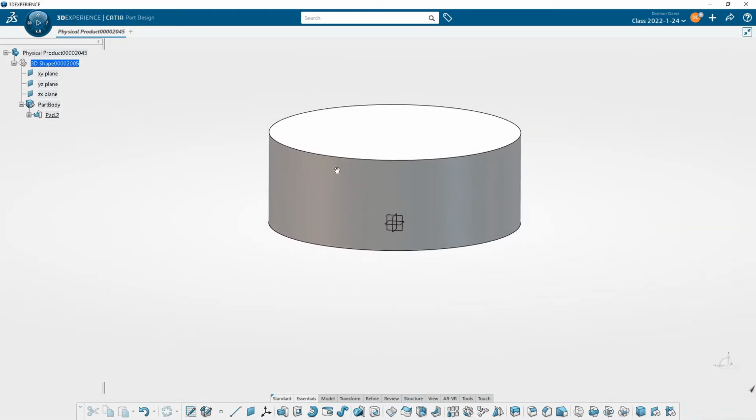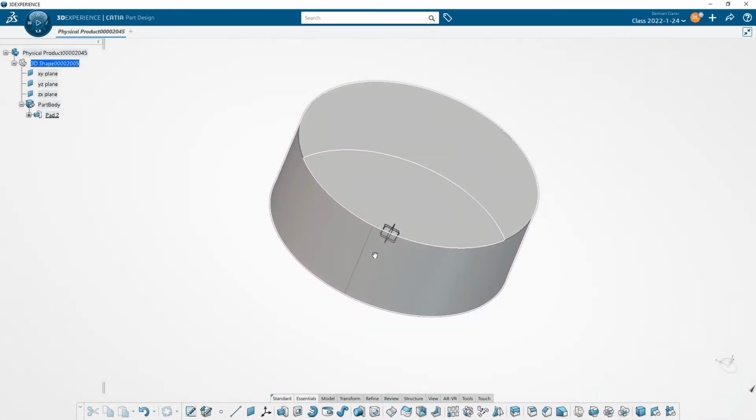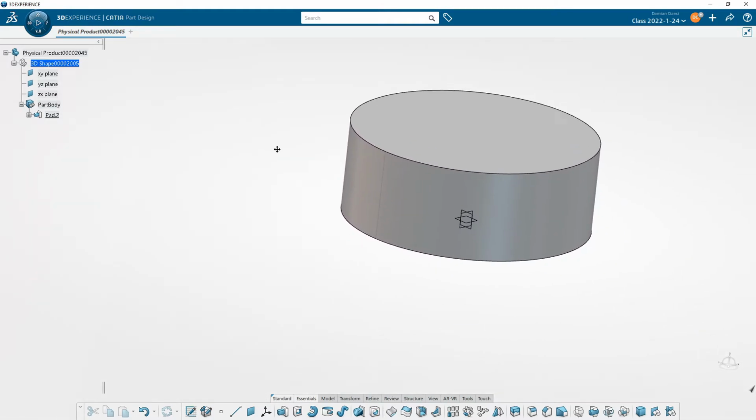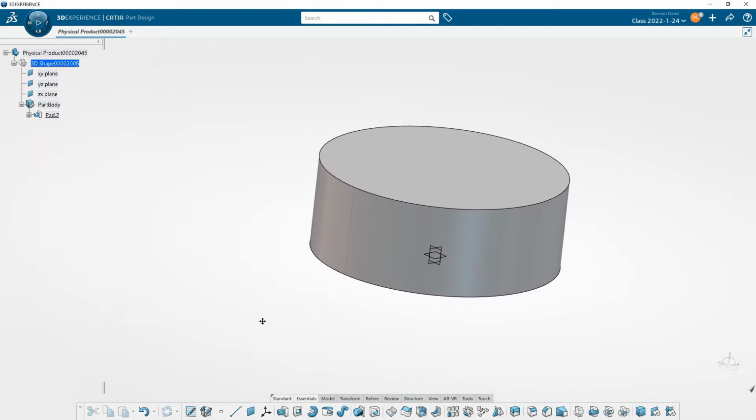As far as movement goes, now that I have something solid here, I can tell you again, I'm holding down mouse button 2 and 3, but let me talk about this just a tiny little bit. When I go to zoom, you're going to find that if you scroll the wheel like you would probably think would be zoom, nothing happens. Not right now. It's used for something else, and I feel that it is rightly so. It's a very good thing for its purpose, I believe. Now, if you hold down just the middle mouse button, button number 2, this is panning. So now I can move around like this. I don't have to reach up and hit a control or an alt key or something like that, like many CAD programs do. I can just grab it, move around.